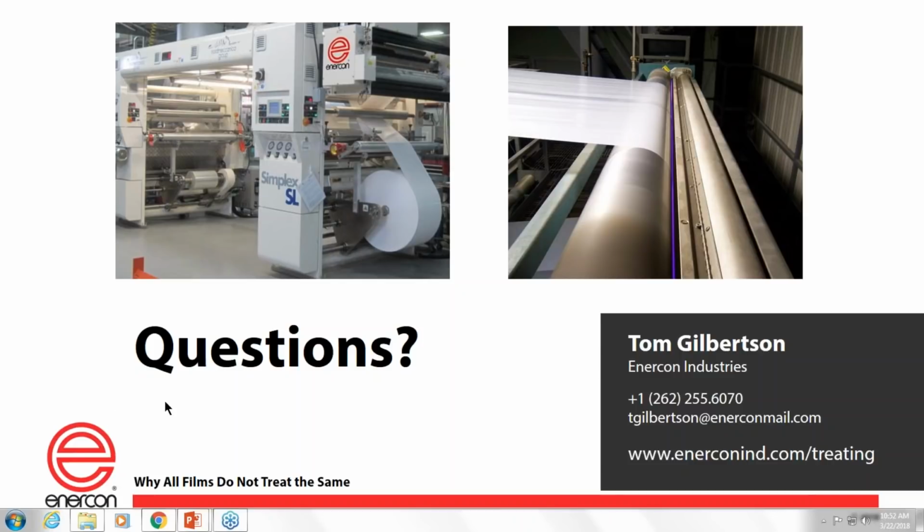So your material's printed, it's treated, it's printed, it's cured, it's wound up. Now you take a sample in the lab, and you might place a sample in a holder, and you take some specific tape, and you apply the tape in a proper way to that printed surface, and you peel it off. And if you get ink pick, meaning ink doesn't stay on, it may fall out of a specification you have, that would be an indicator of failure.